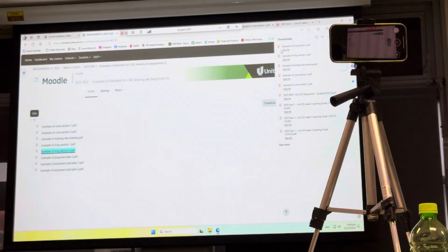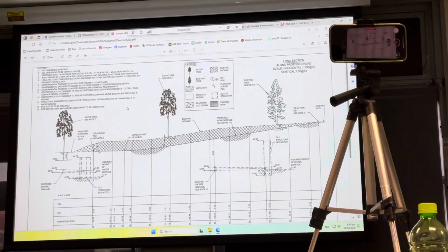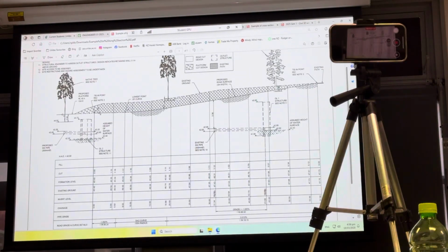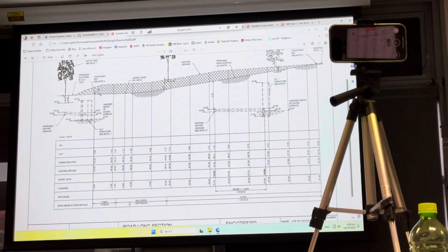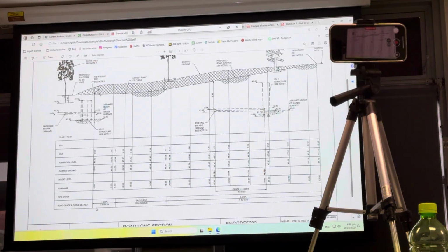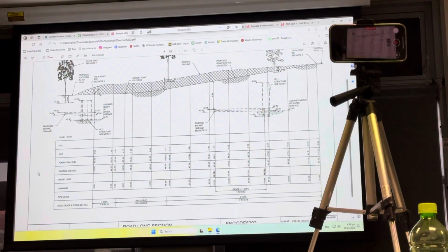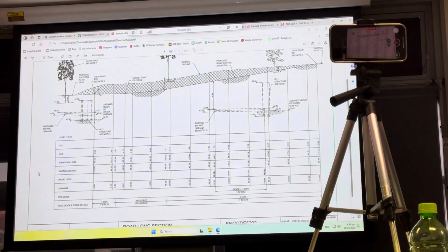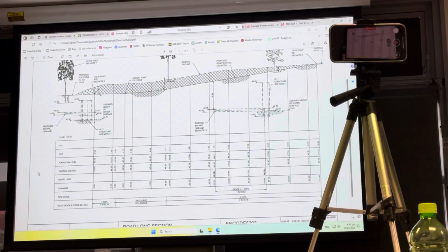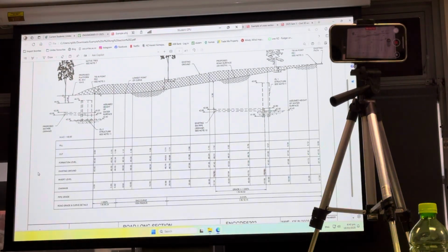There are other long section examples. Here's a better one. This shows the curve. You'll notice down the bottom, now this is interesting, you'll be given this information from Civil 3D. You'll need to replicate that somewhere on your long section. Normally it's in the bottom section. Notice the pipe is there as well. I'm not sure if you've got a pipe, but if you have, you'll have to put that on your drawing with its grade. You don't have a manhole by memory, so you're okay.